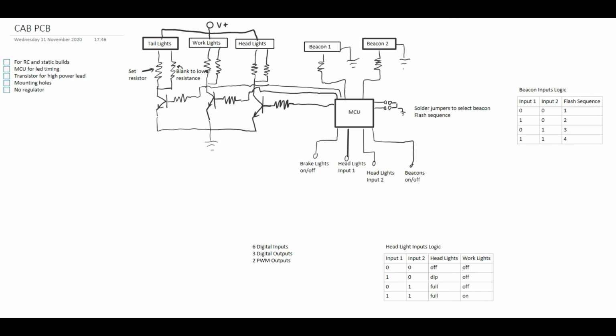All that's left then is the resistors, and going to the transistors, I'll probably use a 1k ohm. I'll probably use 1k for the LED resistors as well. With the empty slot, you can drop that very quickly by putting another resistor in parallel. At the 1k, if your input voltage was 5 volts and your forward voltage of your LED was 1.8, for example, you'd be getting 3.2 milliamps across your LED. So that's not terrible. Wouldn't be using a huge amount of power, so your battery should last a good while. And if it's a static model, that's pretty important. You don't want your batteries running out every 5 minutes.